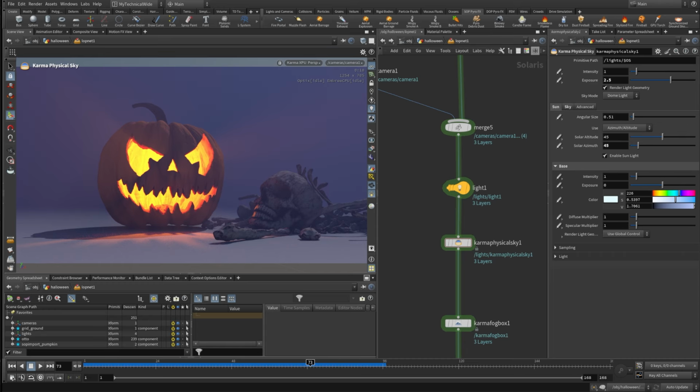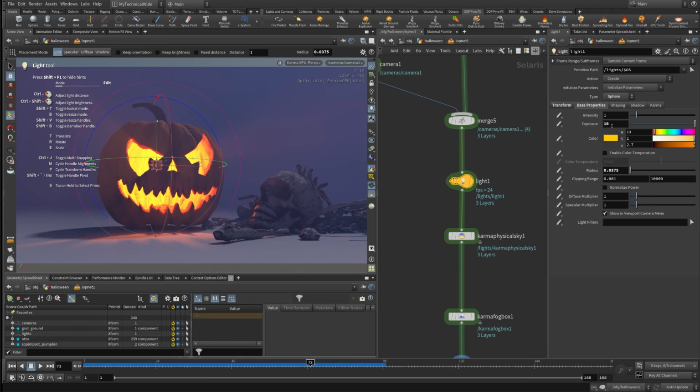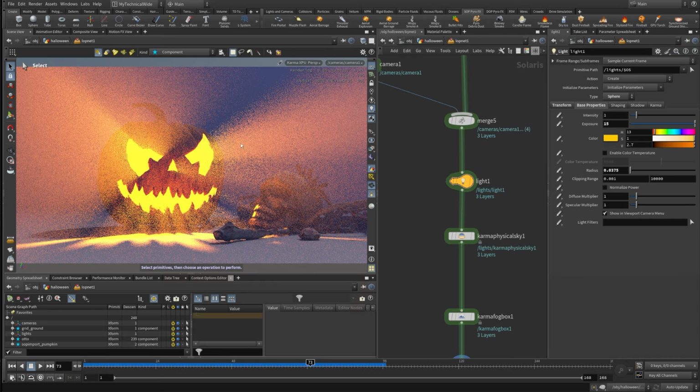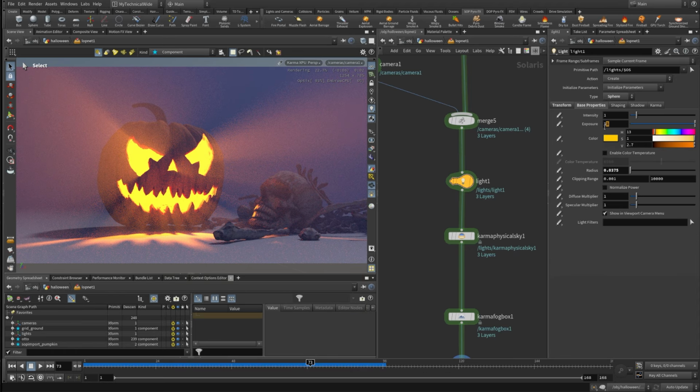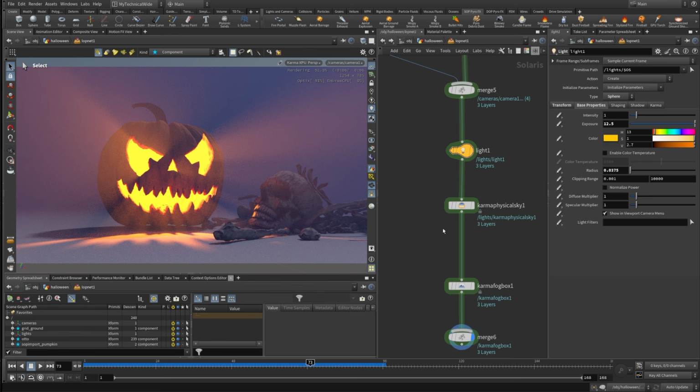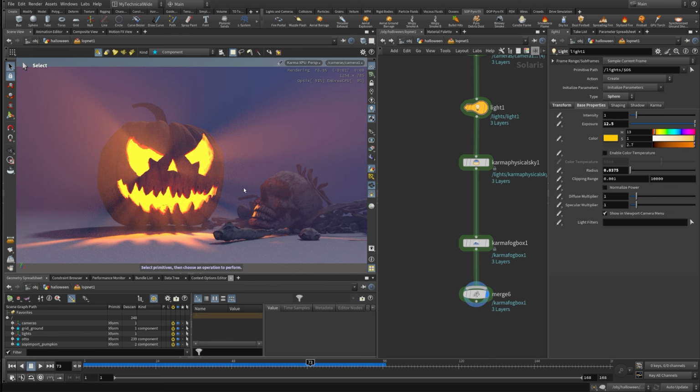The other thing with the sun, I have increased the angular size to have softer shadows in here. If you put this to something like 5, this would soften up the shadow, all right? And also make the highlight a bit bigger. Okay, so this is this. Now let's increase this light back to 15 because we need some more of this. I've been changing these from 12, like 12.5 maybe. But the more we start adding materials and extra things in the scene, the more we'll have to tweak this light. Okay, so this is what we have for this one.